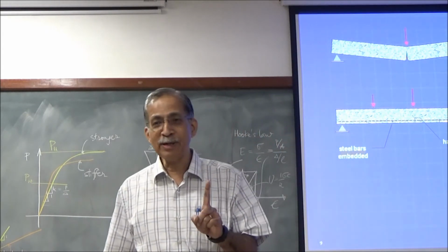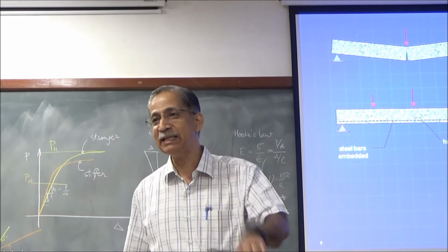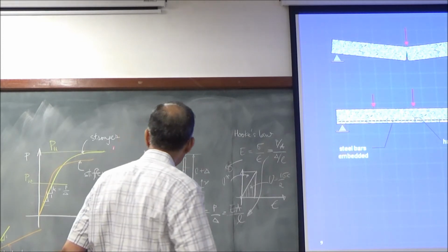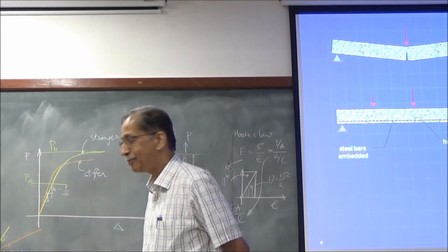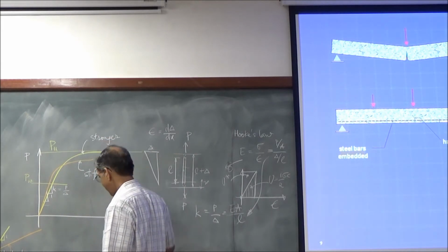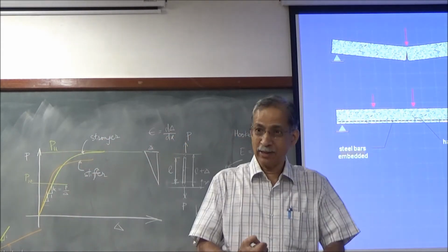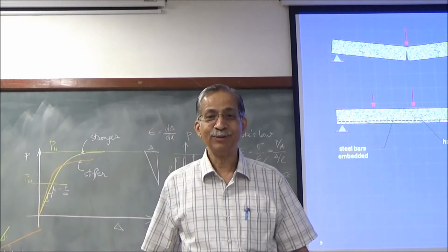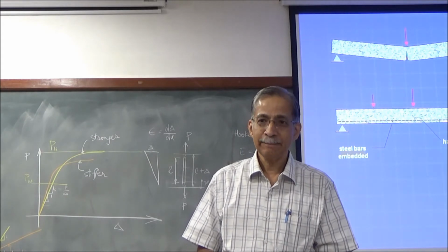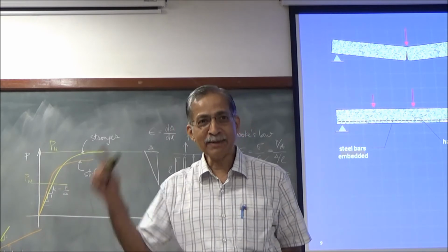Steel contributes not only to tensile strength, it gives another property to concrete which is badly missing in concrete. What is that? You can see it in this graph. That property. Ductility. Concrete is a brittle material. It will break. Steel is a ductile material. It can stretch. So the combination brings ductility. Why is ductility important in buildings? It gives warning. Warning for what? It rings a bell.